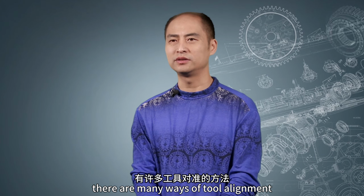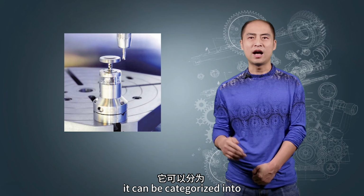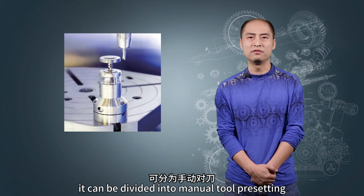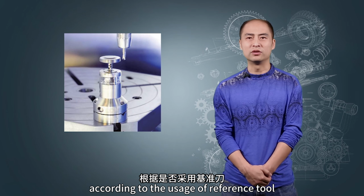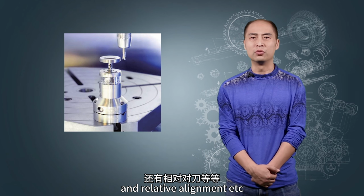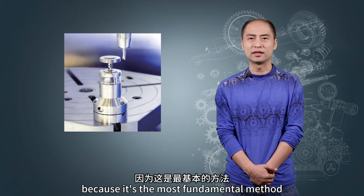There are many ways of tool alignment. According to the precision, it can be categorized into rough alignment and precise alignment. According to the usage of a tool presetter, it can be divided into manual tool presetting and automatic tool presetting. According to the usage of a reference tool, it can be divided into absolute alignment and relative alignment, etc. But all of them need trial cutting for tool setting, because it's the most fundamental method.